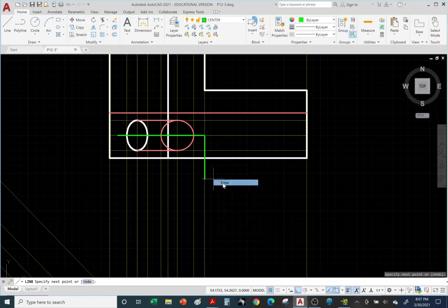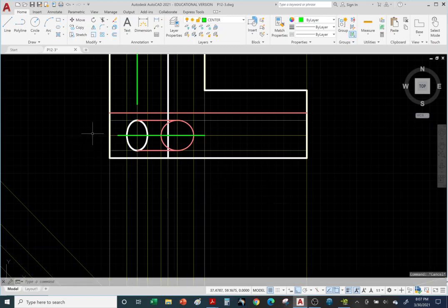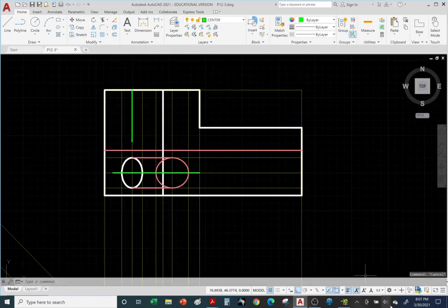Right click enter, and don't forget the vertical center marks. So okay, if we go further beyond, actually looks cleaner than to try and stop here. Whoa, way too big, way too large. Let me hit escape. Okay, so let me temporarily turn off object snap. Lost control there for a minute, and I'll just use the grips to change the length. There it is. Hit escape to deselect.